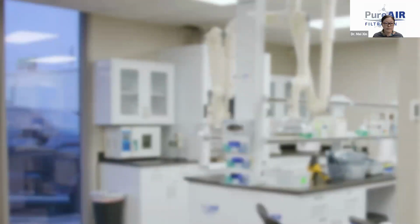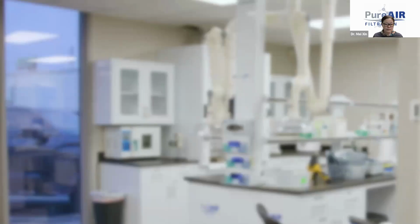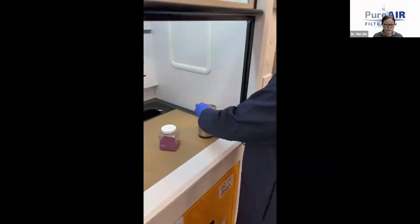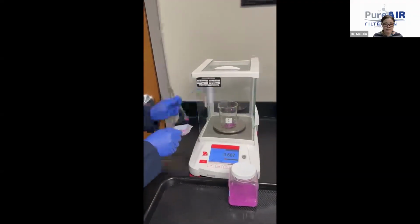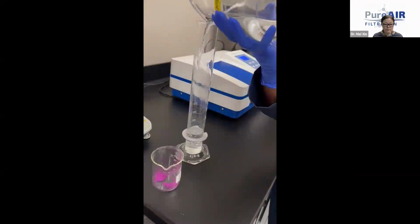Prior to the analysis, the lab staff records the date, time, and sample identification in the lab book. Then we carefully select the media samples directly from the customer's sample bag and crush them into fine powder to increase the surface area to ensure complete chemical extraction. Next, we weigh a certain number of grams of the crushed media and soak it in deionized water in a beaker. Stir it well.